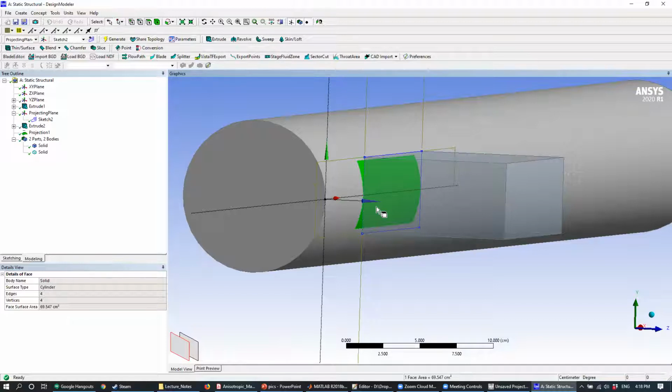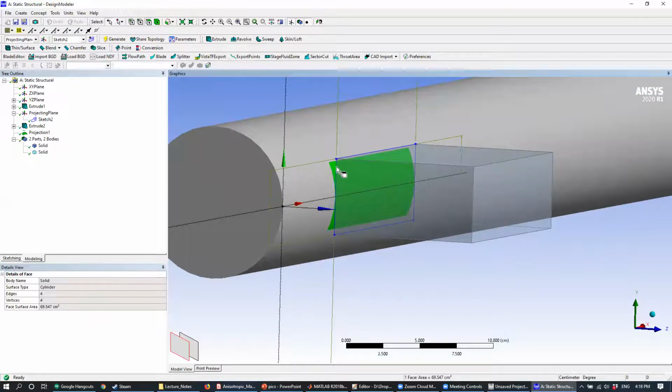Okay? So I will say that it's a little bit different than how we did Ansys Activity 3, because in Ansys Activity 3, that extra surface was actually created as another whole body that was kind of bonded to our structure. Okay? So this is a little bit cleaner in that this is kind of a new selectable surface, but it doesn't actually have any physical dimensions. So it basically just allows us to select certain parts without adding any thickness, right?